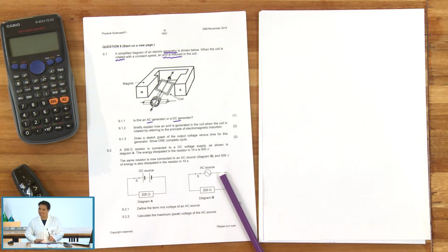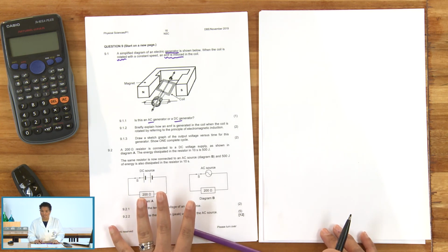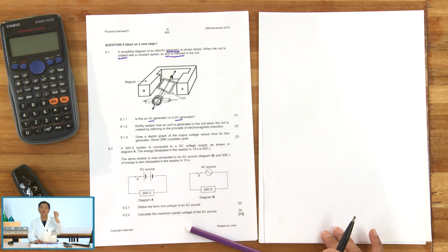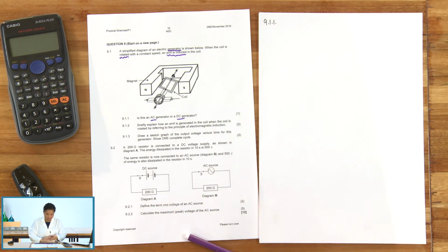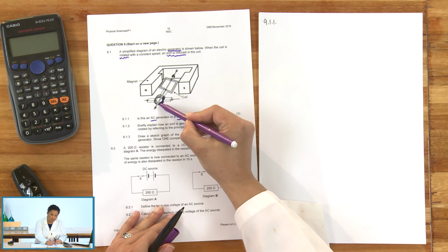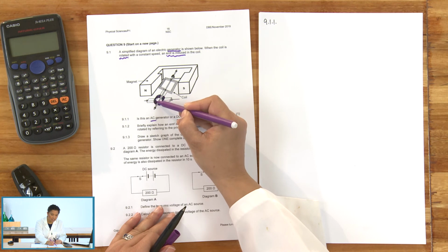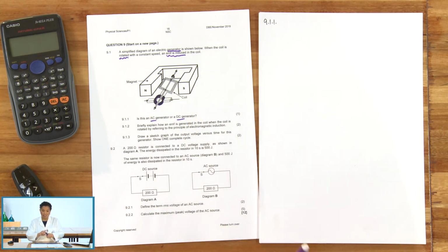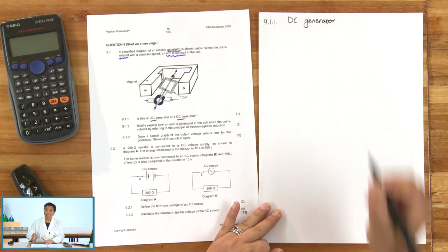Grade 12s. We've covered how to figure out if it's AC or DC. They've told us that it's a generator, and we now need to decide. And the deciding component of an AC or DC generator is whether we have 2 slip rings or whether we have 1 split ring commutator. And it is quite clear. Over there we can see that little hamburger roll without the patty. We can see we have a split ring commutator, and that's indicative of a DC generator. That gets you 1 mark.